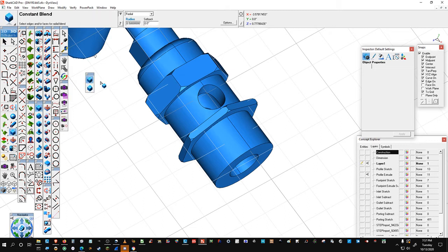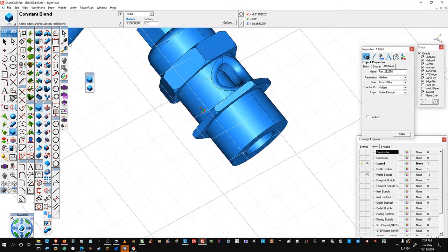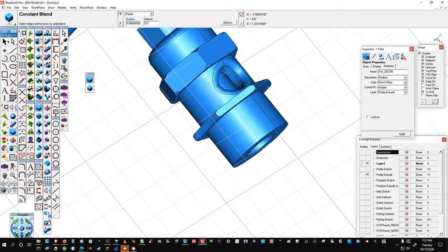There's fillet. Forgive me for not remembering where it was. And we'll just do 0.5. That'll work. We'll click that line. We'll flip it over, and you would never do a fillet on something like this unless it was molded plastic. But anyway, it'll get the point across.